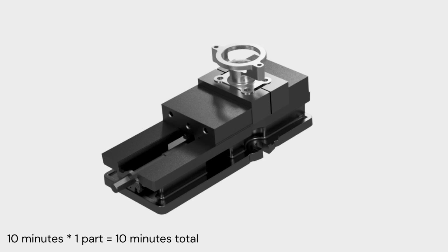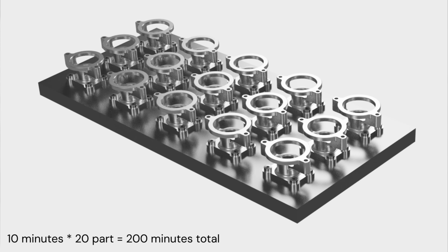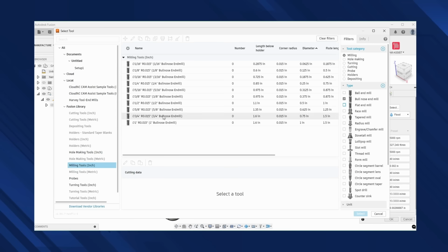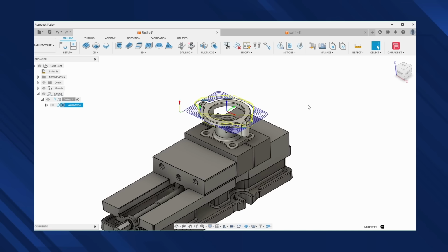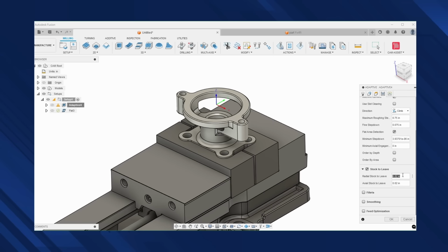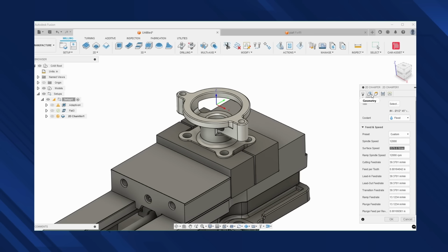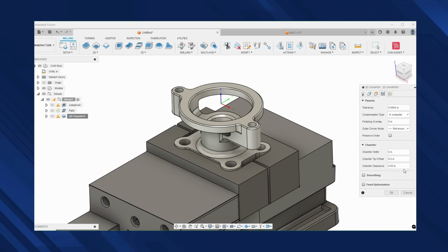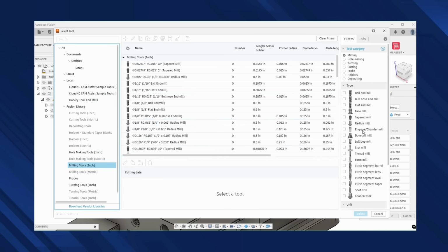If the part has a short cycle time and we don't have someone available to stand at the machine all day, it may be a good idea to run several parts at once. If one operation is really long and the other is really short, it may be a good idea to see if we can divide those toolpaths more evenly between operations or balance the load through quantity of parts per machine. All of this information must be considered when developing our manufacturing plan, because this information will determine if our plan aligns with our company's goals.